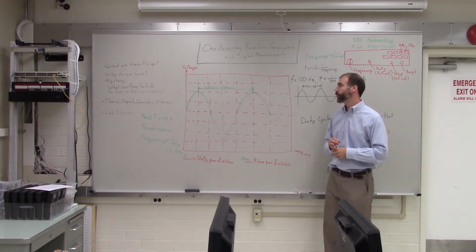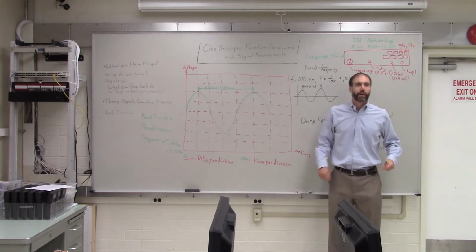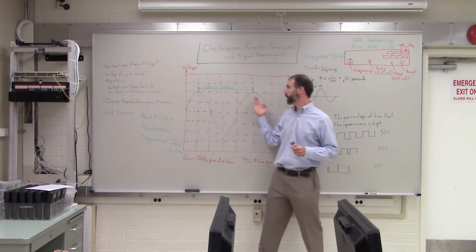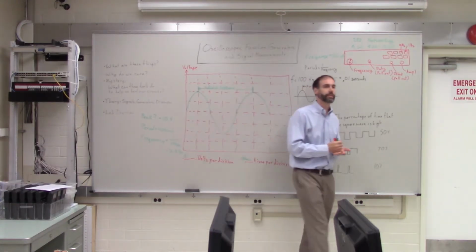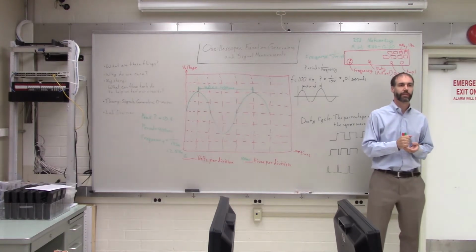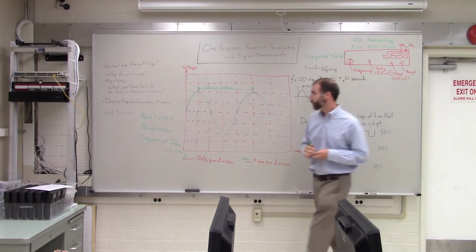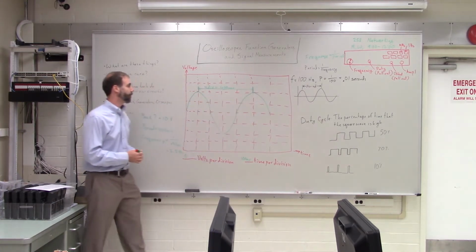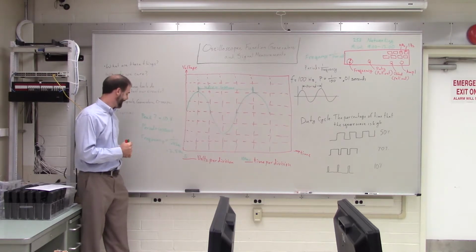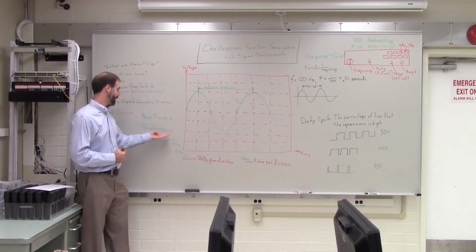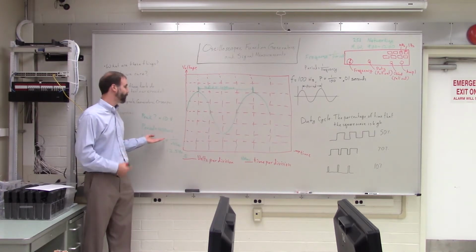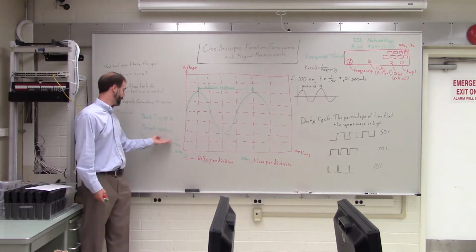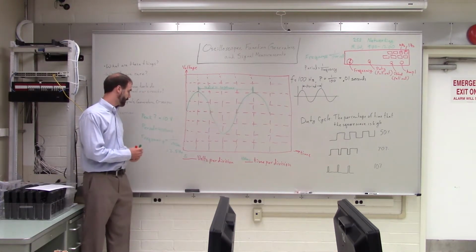And these are actually really important because, sorry, before I go on, does anybody have questions about how we did these measurements or how we did the calculations? So just to recap, we counted 4 divisions at 100 milliseconds each. So that came out to be 400 milliseconds. 400 milliseconds is the same as 0.4 seconds. So we said the frequency was 1 over the period, so 1 over 0.4, and that comes out to be 2.5.